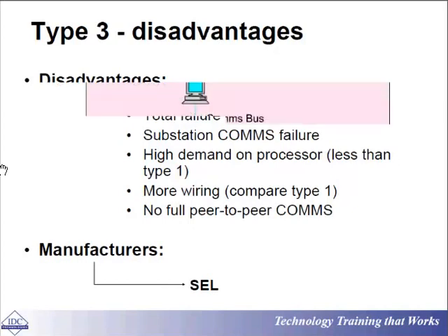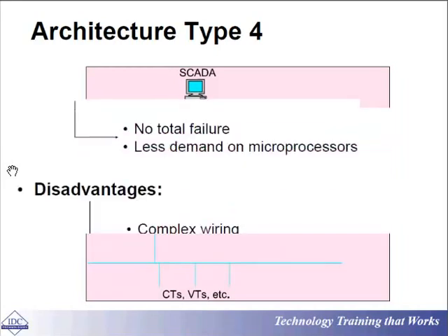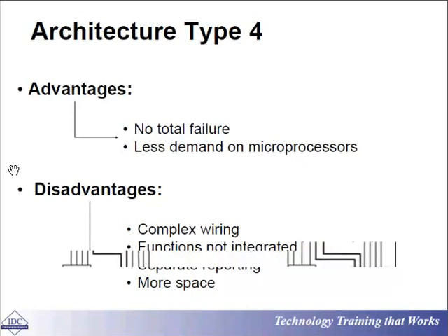All right, so is there any other way? Yes, it can be SCADA-based. Again, I have got those IEDs and relays and everything, but this time everything is controlled via the RTUs, via the PLCs, and again connected to the comms bus. Advantages, yes, again, less demand on microprocessors and no total failure because this time the relay is not alone. But again, you will have more complex wiring and separate reporting and more space would be required.